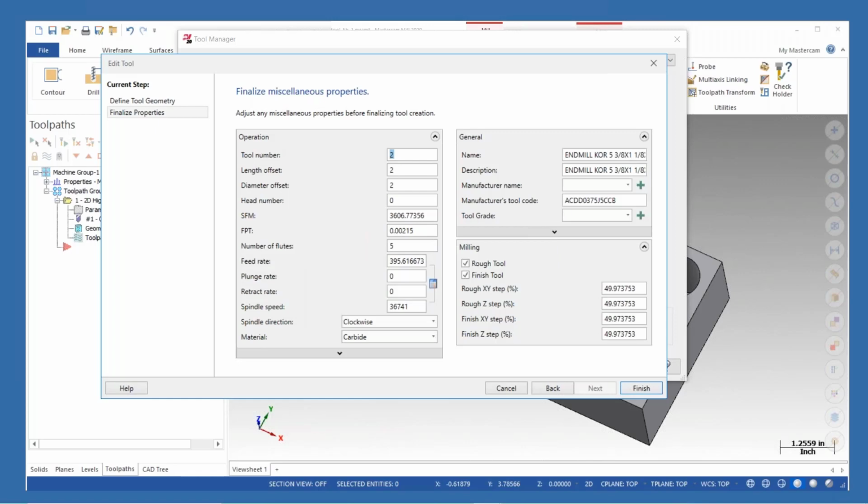It's got a surface feet and a feet per tooth that I'm going to tell you aren't correct. So I'm going to go ahead and set that. The machining cloud does not import correct speeds and feeds. And we could spend 10 workshops talking about speeds and feeds and the correct speeds and feeds. There is no correct number. I can't give you the magic bullet. Every machine is different. Every holder is different. Every tool is going to be different. But I'm going to go in here and set these to somewhat more accurate numbers.